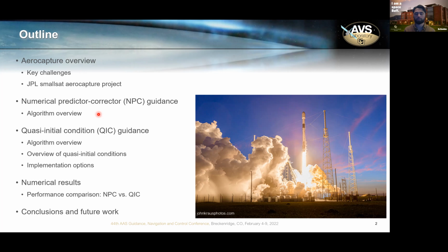Once that optimal Jettison time is computed, we also numerically estimate the sensitivity of the Jettison time to the altitude, velocity, and flight path angle at atmospheric entry. And so this requires one or more additional numerical propagations in this step. And then we repeat this whole process for a range of k values, a range of atmospheric scale factors. And this, for example, might be ranging from 0.5 to 1.5.